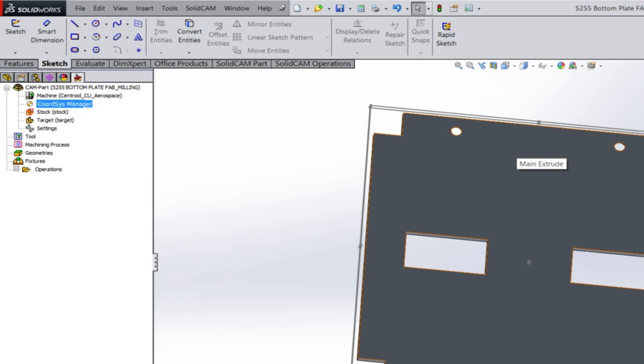So when do we use an edge finder? When we're trying to set up coordinate systems. Right. When you have a smooth surface that's been machined and it's accurate. When you don't have a smooth surface and it's not accurate and it hasn't been machined, just go ahead and use a drill bit, because the offset of your eyes should not exceed this little gap here. Now, if you don't trust yourself, or you're working really fast and you're not taking care, you may exceed this 1/16 of an inch in error, right?